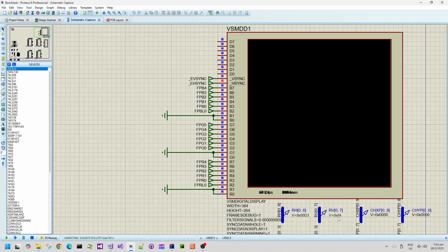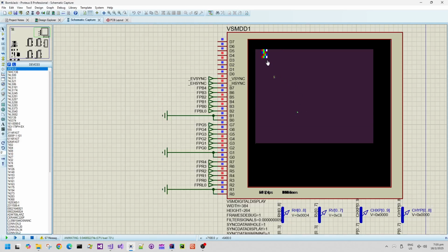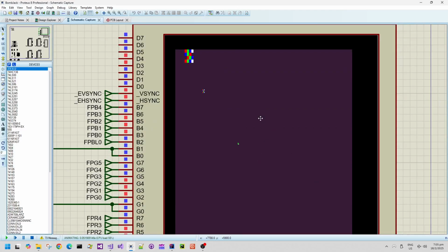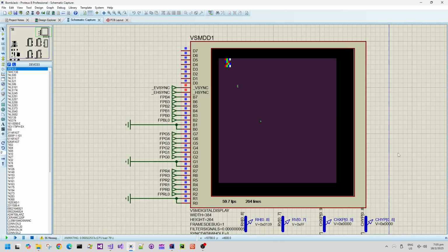There are 2 frame buffers, and they need to be cleared first of all before the logic can then start rendering sprite pixels into alternate frame buffers. So I have 3 scaled sprites in the test data. One is scaled up 4 times, one is normal scale, and one is scaled down by half. And the pixels are red, green, and blue, and then white, and then transparent.